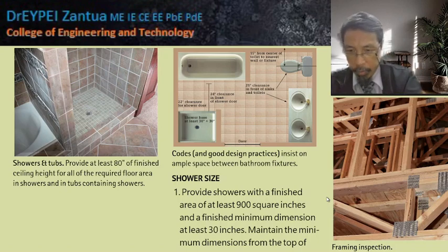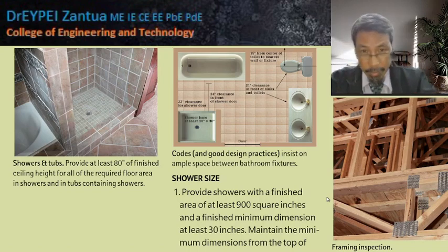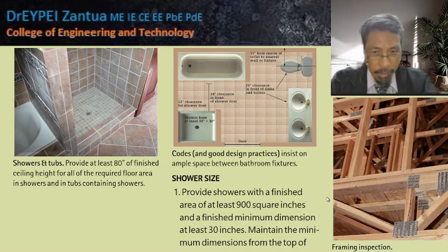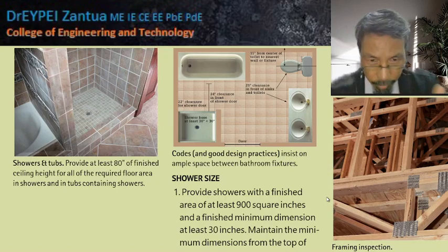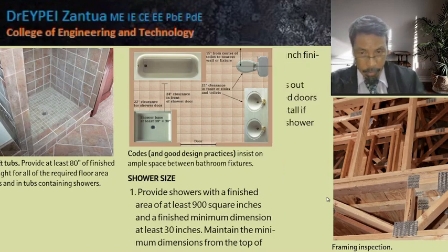If we compute that, 2.5 feet is about 762 millimeters, so that is actually correct. 760 or 762: 760, I think, in the Master Plumber code, and in the Sanitary Engineer code, that is 762. So that is the actual. The corresponding provisions are still there in our country for shower size.